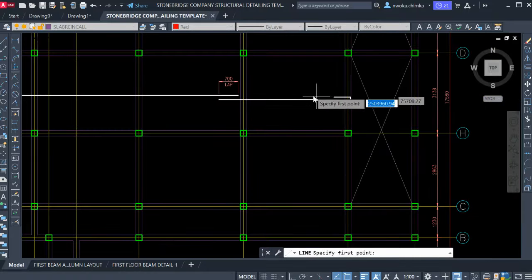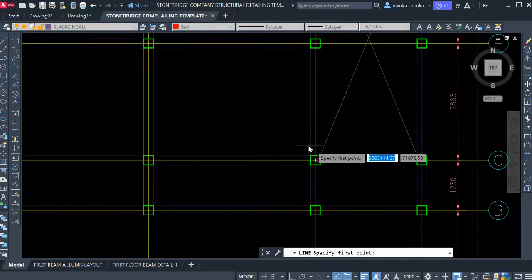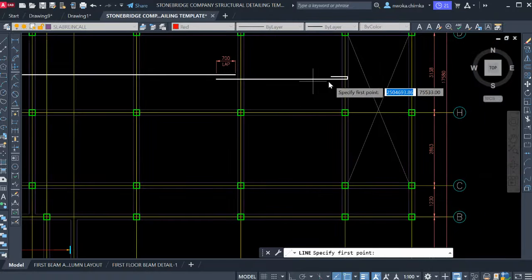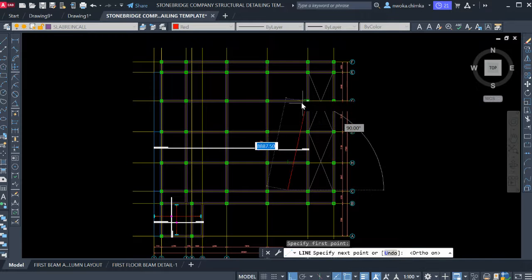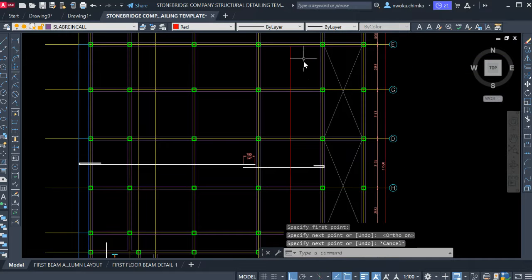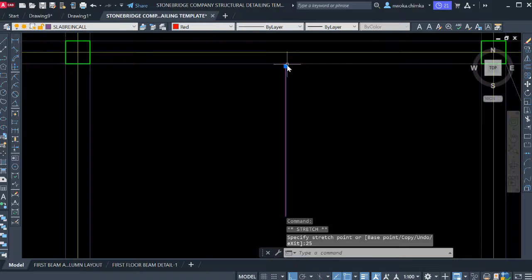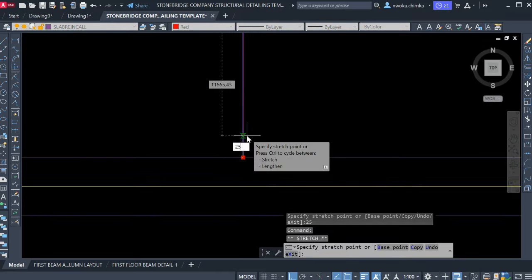So this reinforcement runs all the way down here. When it's trying to pass this point, it finds a slab, so it will have to stop at this point for the next reinforcement to continue, which will cross into this slab. So this reinforcement runs from this point all the way down to this point, where we have our staircase void ending. Now we have to remove our cover for the slab of 25, which we used for the design of this structure, and also remove this slab 25 also.